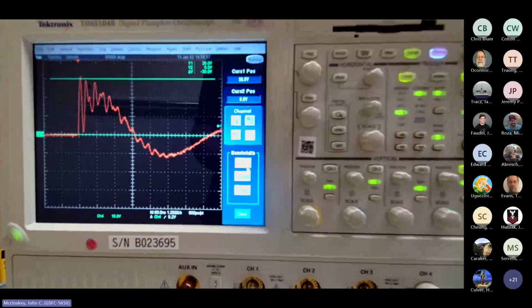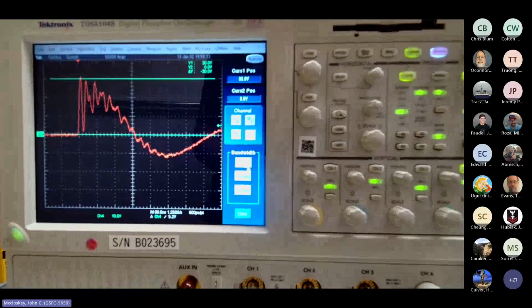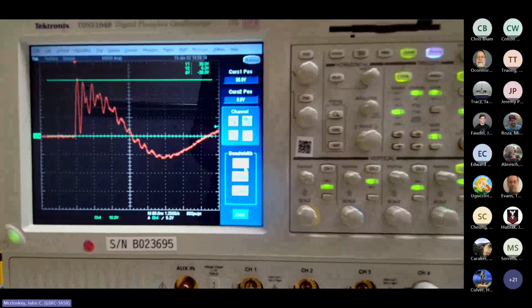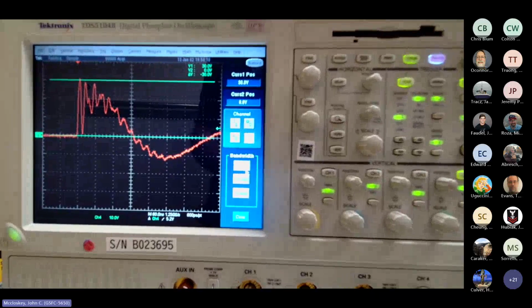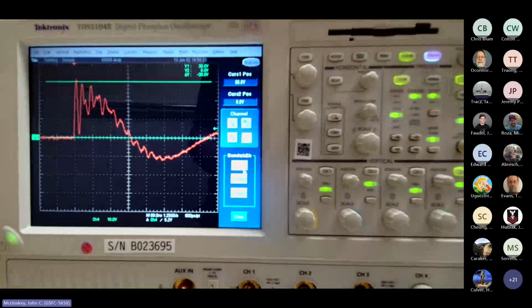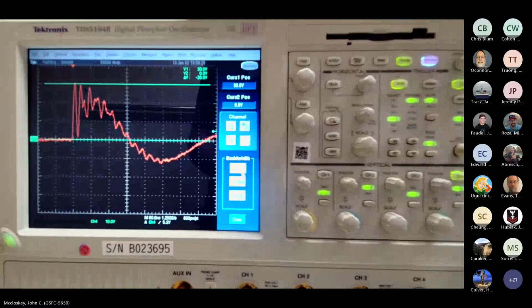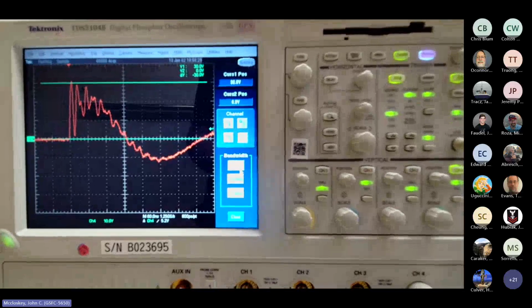if your power system architecture is such that you've got a beefy capacitance at the distribution point that's just going to absorb the energy from any of these turn on, turn off transients, all this may go away. All this may be moot. I'll share direct experience here on JWST.